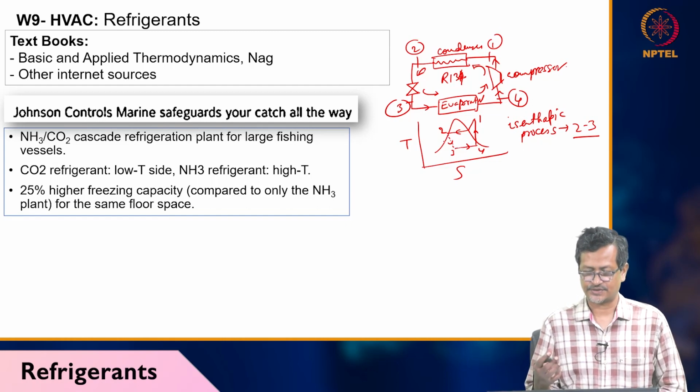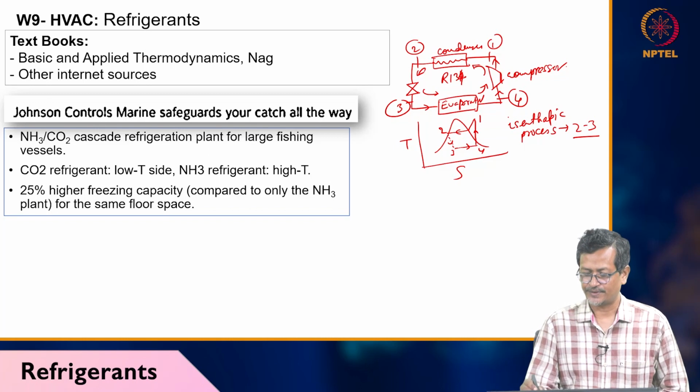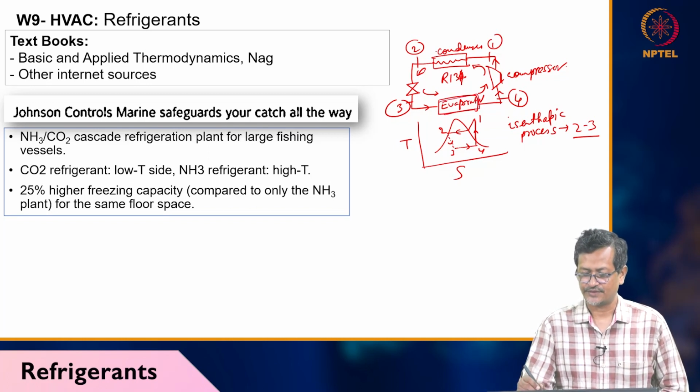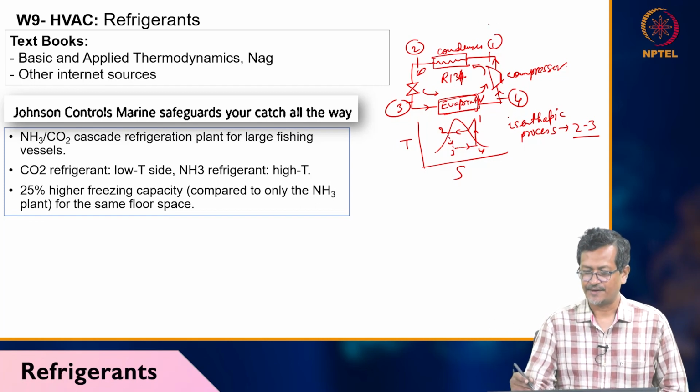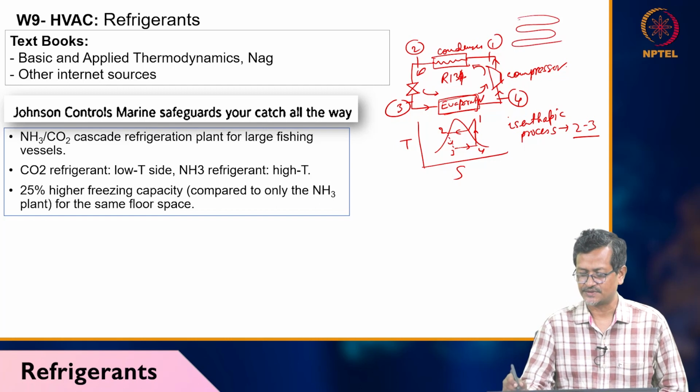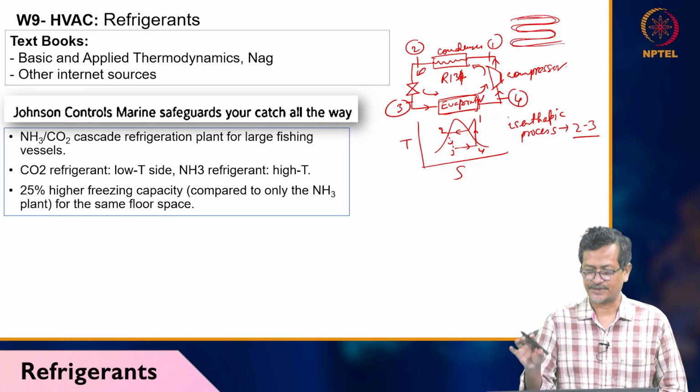So condensed liquid will be passed through a narrow channel, then evaporation will be happening. The evaporator will be inside your room or inside your refrigerator, and the condenser part will be outside. If you see any refrigerator system at your home, or any air conditioning system, at the backside there will be serpentine pipes. Normally it will be copper pipe, and it will be releasing lots of heat, and if you touch it, the temperature will be very high.